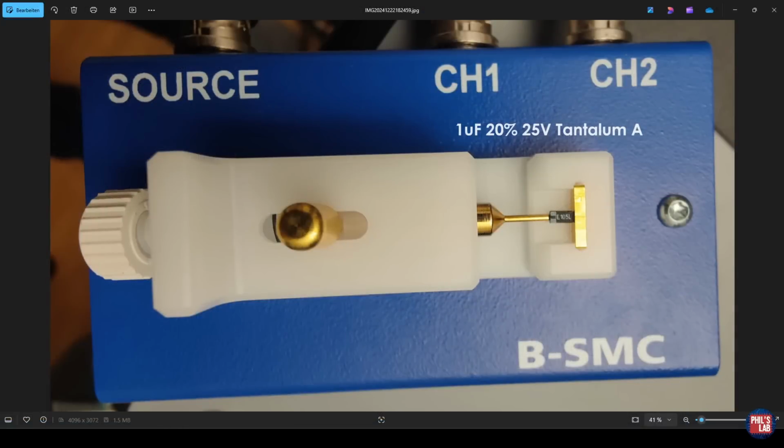The next part I'd like to measure with you is a tantalum type capacitor. So a polarized type capacitor, oftentimes not viewed particularly favorably for various reasons. This one is also at 1 microfarad nominally, 20% tolerance. It's this time rated to 25 volts. Again, a tantalum capacitor, and the package size is a Tantalum A. Polarity, especially when you're DC biasing this, is important, and we have the positive, so the anode marked for this capacitor. Let's go over and measure this.